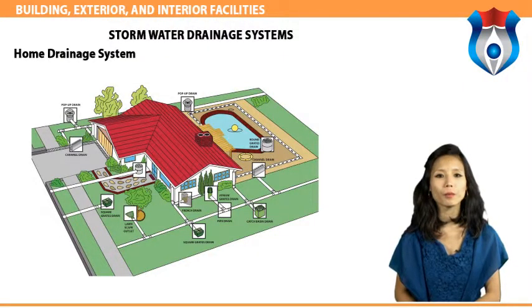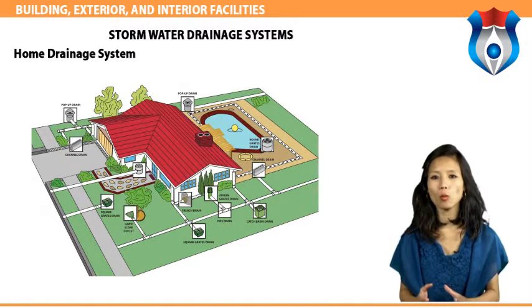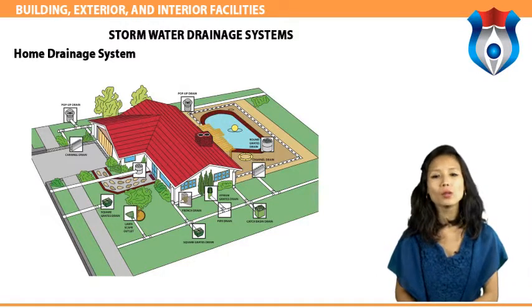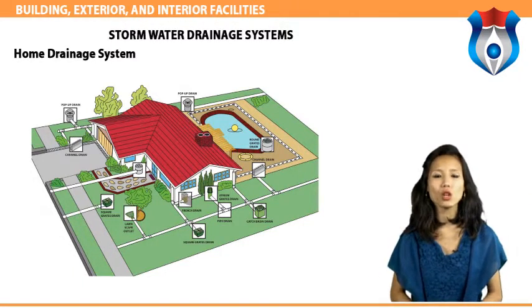Home drainage system. The sanitary line deals with all water disposed of inside the home. Water from showers, toilets, sinks, dishwashers, clothes washers and floor drains is channeled to a line on the basement floor. This line is connected to a larger sanitary sewer pipe located under the street.